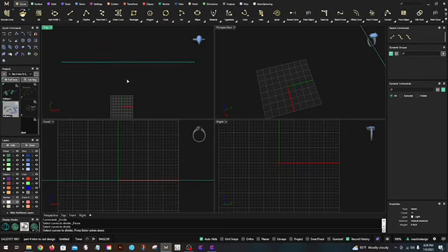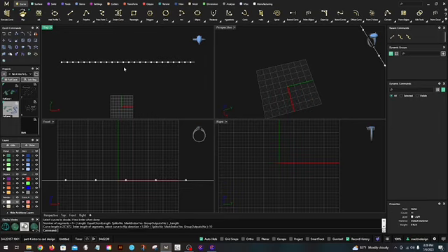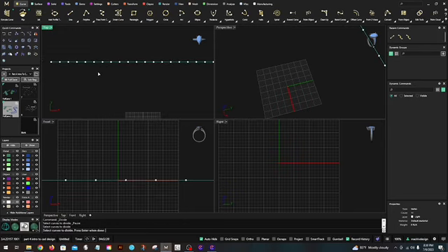So we're going to do this and press enter. Curve length is 237.672. Enter the length of the segments. All right, and then you can split it if you want. That's interesting. Okay, so let's just do 10 millimeters. All right, and see, it divides the curve up in the segments, but it did not split it.